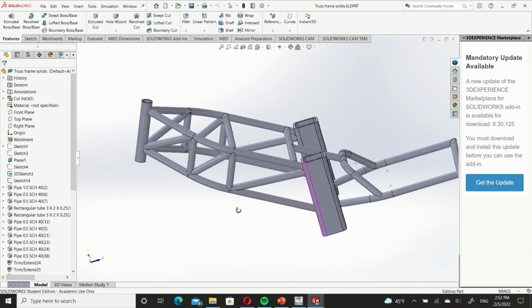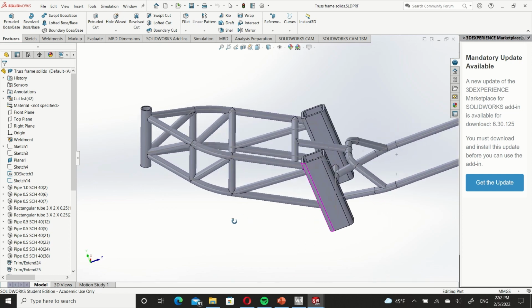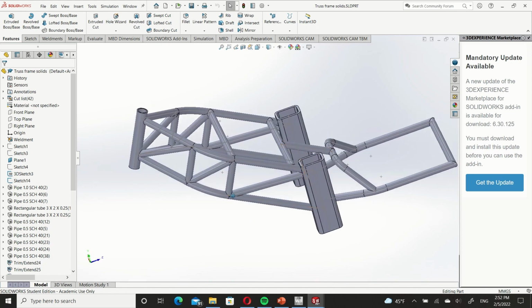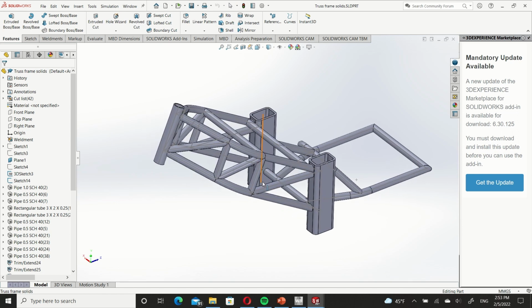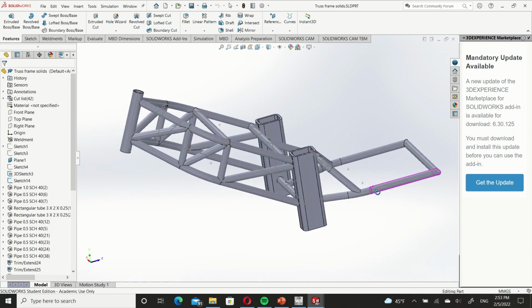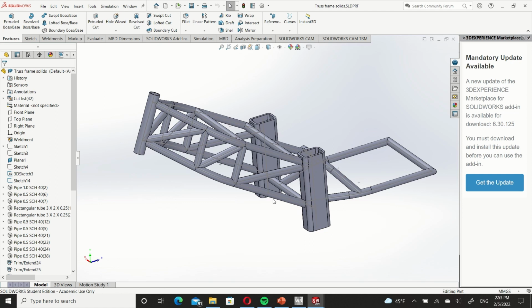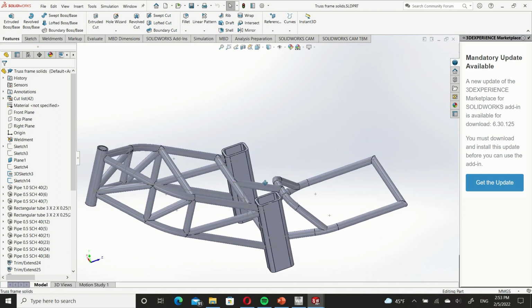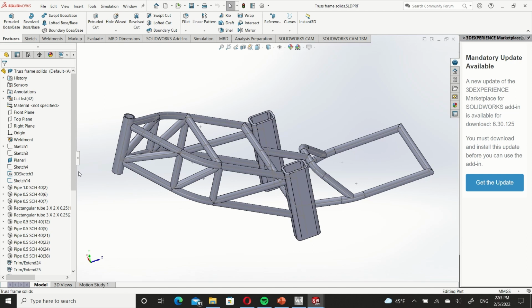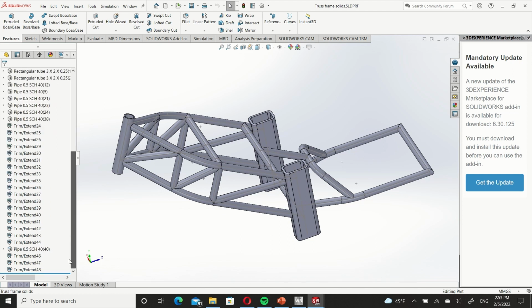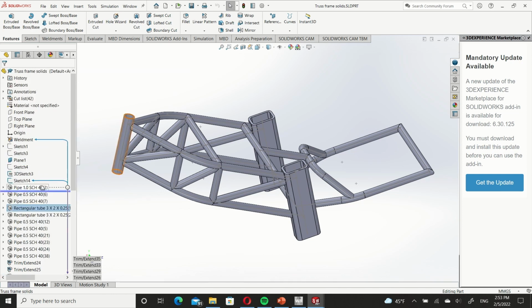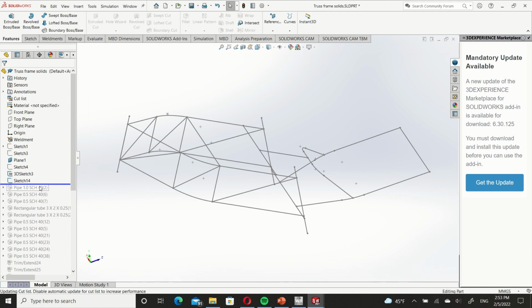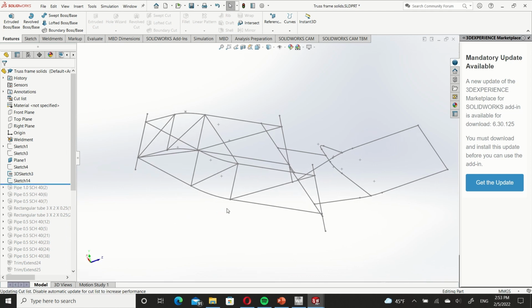So we're going to start out with this model in SolidWorks. This is all done up. Instead of a spring, I just put a weldment here, but that's fine. And we have all this nice 3D modeling stuff, and we will not be able to take that into ANSYS. Unfortunately, ANSYS does not appreciate built-out solid geometry when taking into analysis with beams. So we're essentially going to have to roll back all of these solid bodies until we're left with just the original 3D sketch.